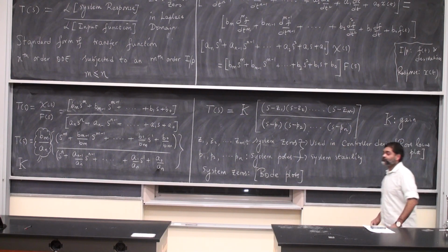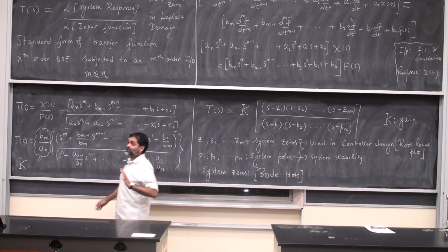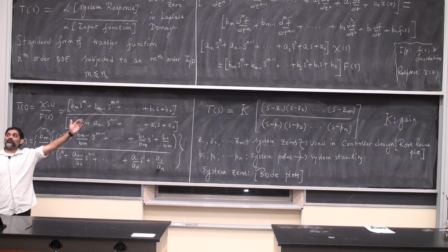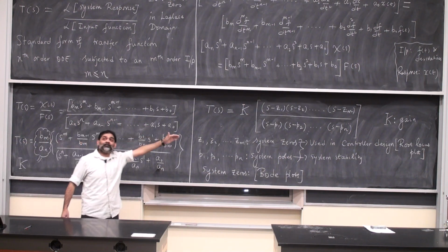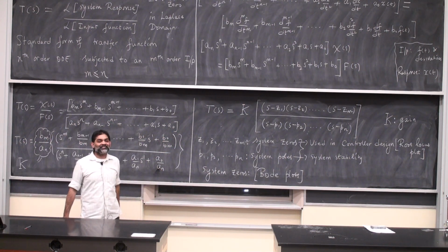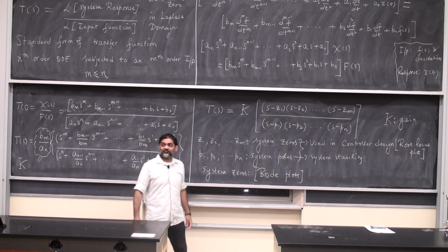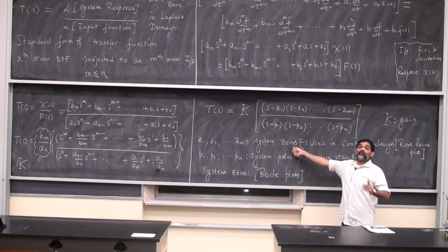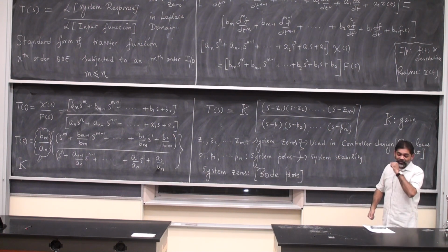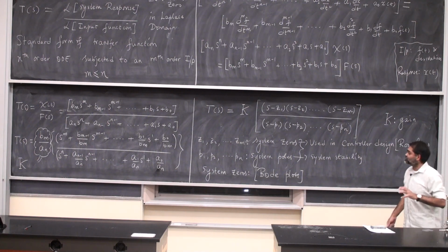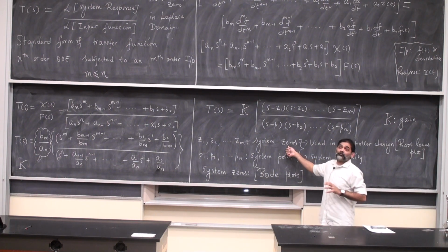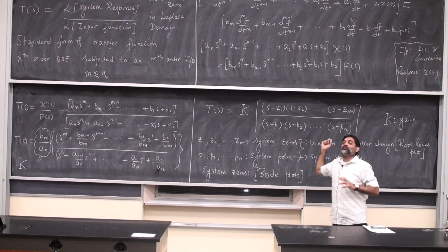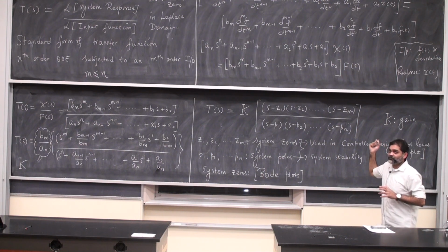We're going to do this next week. All right. So this is a standard representation. Why do we call the Z1, Z2s as zeros? Is because if S is equal to Z1, the transfer function becomes 0. It's as simple and elegant as that. Once again, I'm not going to write this out. Why do we call them as system zeros? In my lecture notes, I've spelled it out clearly. Please read my lecture notes. Spend some time looking at it at least. The system zeros are called that way because if I substitute S is equal to Z1, for example, the transfer function becomes equal to 0. Okay? That's why it's called a system zero.